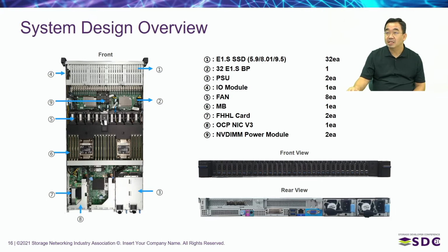The Poseidon system is the latest EDSFF E1.S SSD reference system optimized for an NVMe Fabric target node. It is a 1U height PCIe Gen4-based Ice Lake 2-socket system and utilizes the latest Samsung PM983 SSDs. The Samsung PM983 SSD supports 4 lanes of PCIe Gen4 and delivers up to 6 GB/s of I/O performance.